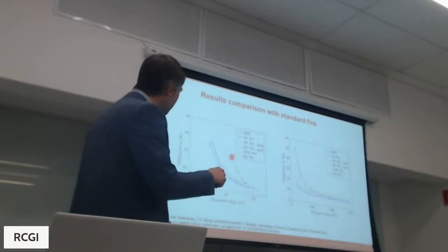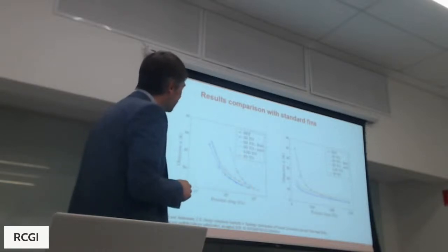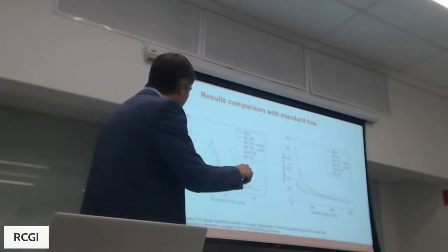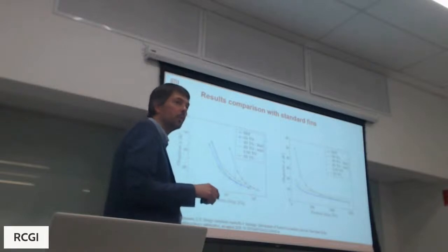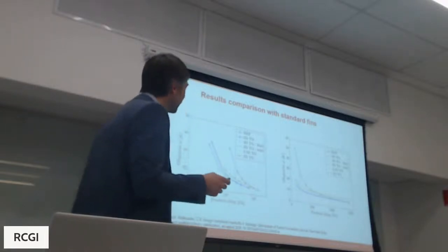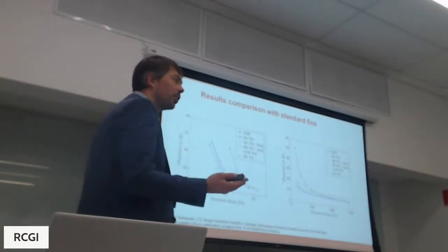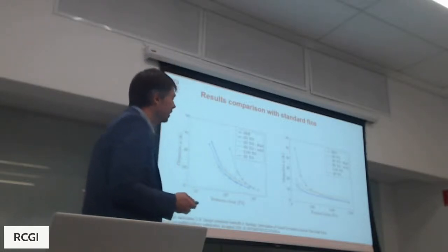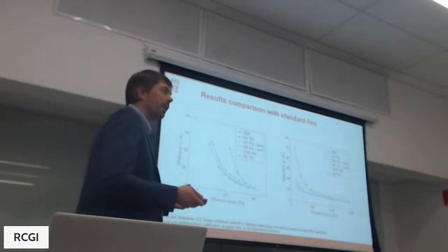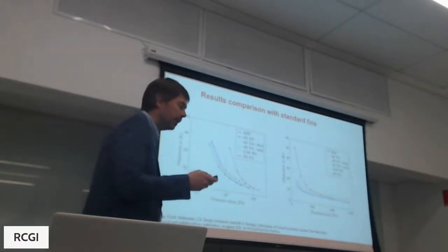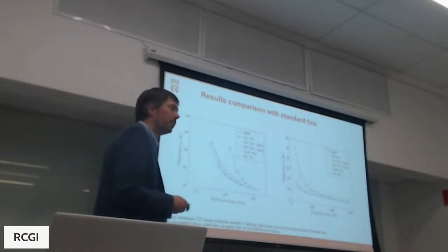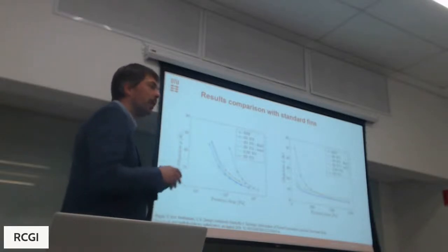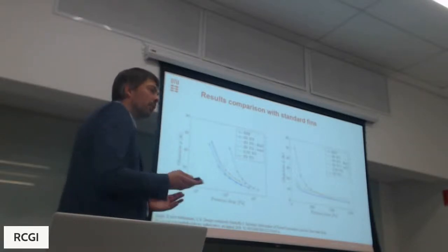So it's actually pretty successful, the design that we already initially started at optimizing. And at the point we're optimizing somewhere over here, it's actually hard to beat it with the resolution we have available. But what we can optimize is the pressure drop, and that is also where we can gain from trying to lower in the emissions, that the pumping power that is needed to actually run the heat sink can be reduced by these methods that we present. It's difficult to bring down the average temperature, but we can maintain it at the same level at a lower pumping cost, so we also have a win.